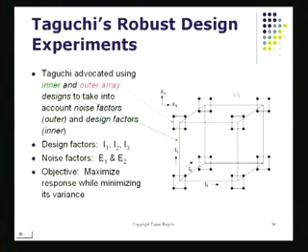What Taguchi suggested was that you construct two arrays, two matrices. One will be the inner matrix, that's the green matrix. The green matrix is inside the big box. The big box is the design matrix. This is the one that has I1, I2 and I3, three design variables. And with that, we are able to generate 8 different types of prototypes if each of these factors is looking at 2 levels. If you're manipulating these different design factors at 2 levels each, I'll end up with these 8 possibilities. 2 cubed, that is 8. That's the construction of the inner array.